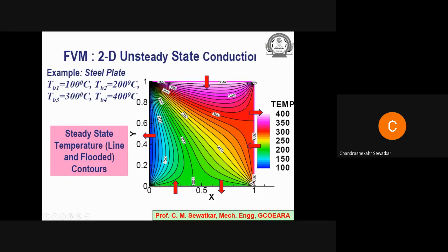So this is how we can obtain the temperature distribution, and we can indicate the temperature. This is one way of indicating the temperature distribution, because we cannot understand anything from the numbers as such. This solution has been especially obtained for 100 by 100 grid points along the x and y direction. If you look at 100 by 100, 10,000 points, if you simply look at the data, you feel that it is almost junk. But if you plot it, you can understand the variation of the temperature. So the purpose here is to understand the variation of the temperature.